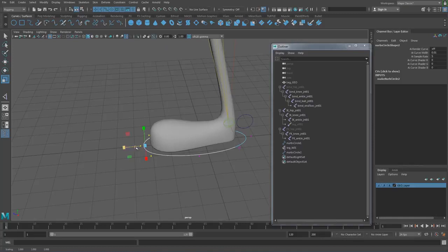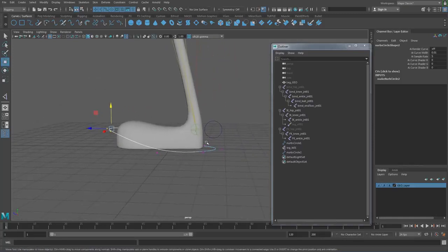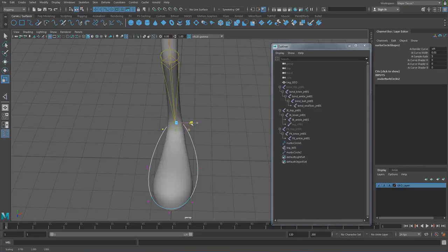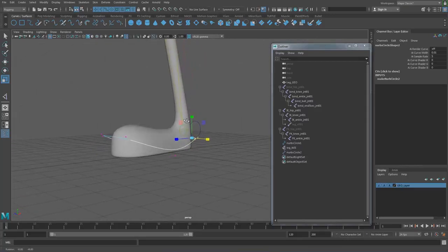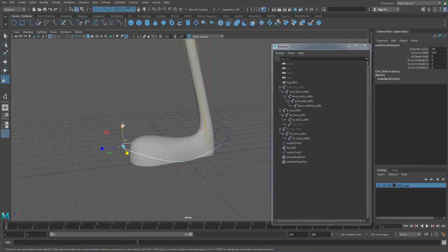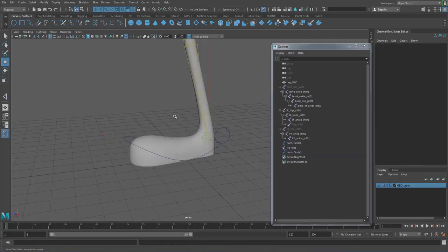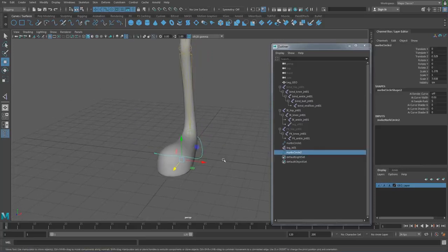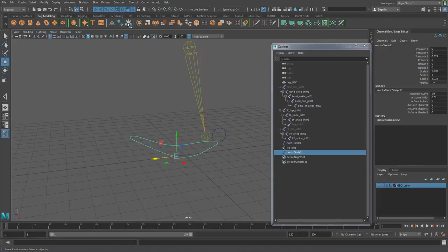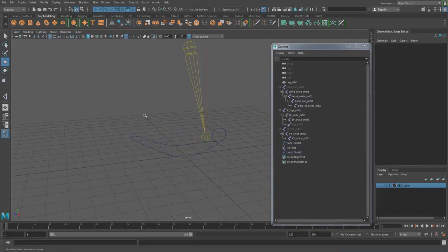Going to just spend a bit of time designing this. Again, the design is completely up to you. I try and make them not all so flat, just so the animator can actually select them a little bit easier. But that's really the only tip I have for the design of these particular controls. Put them in a location that makes sense, but also make them so that they're easy to select. Okay, so something like that as well. Perfect. So now that's done, I'm just going to turn off my geometry because I know that this control works. I'm going to freeze my transformations and delete my history.